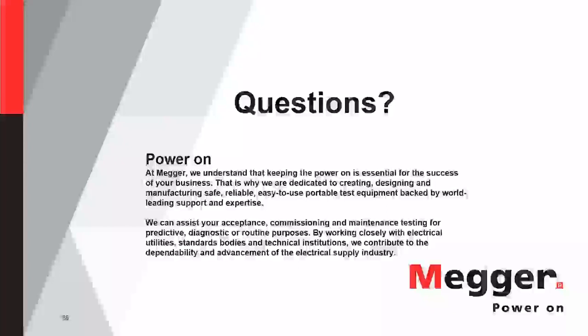Let's look at an SF6 circuit breaker. What we're actually measuring is not the main contact. We're actually measuring that arcing contact, because that's the first metal to touch and the last metal to separate during our timing. So if that arcing contact does wear away, and say it was originally a length of 20 millimeters or so, and now it's down to 10 millimeters, you could see where that one phase is operating a little bit slower than the other ones.